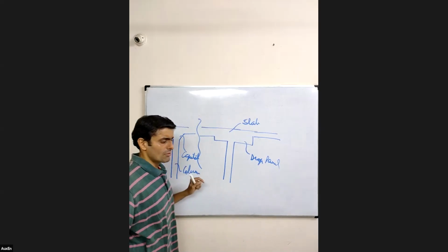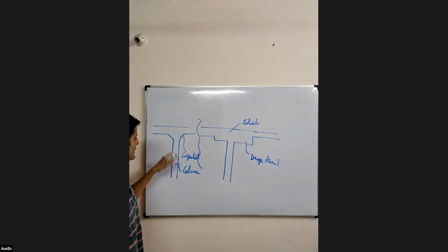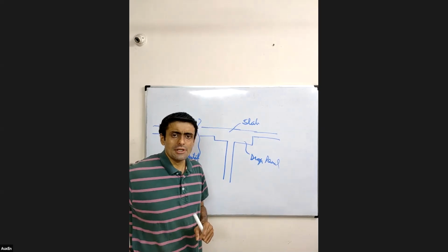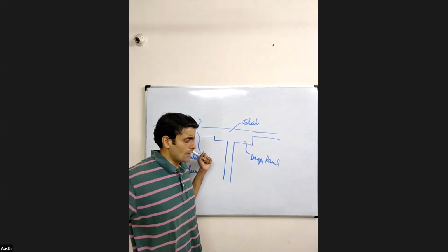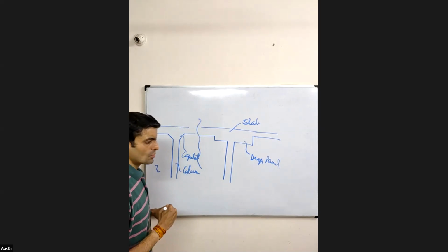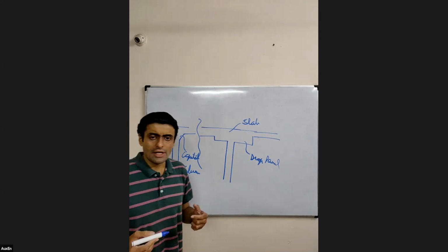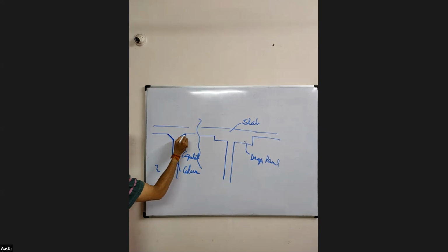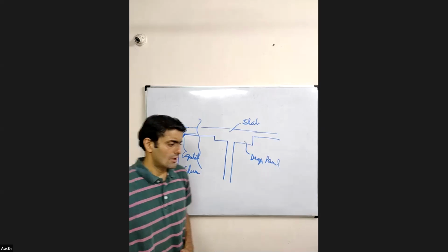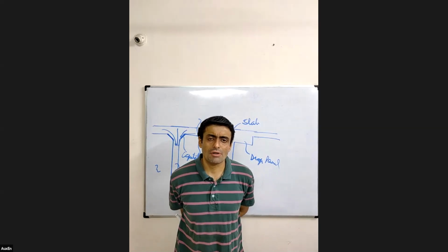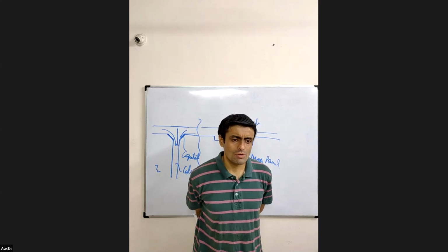Okay, so there was some question from I think Mr. Sahas. He was asking why will there not be very high stress concentration near the slab column junction of this column capital? So yes, there of course would be high stress concentration. So to decrease our stress concentration, we are providing this slope over here. Do you see this? Why we are providing slope over here? So that the load smoothly transfers to our column. Therefore, we are providing this flared shape so that our load smoothly flows to our column. All right.